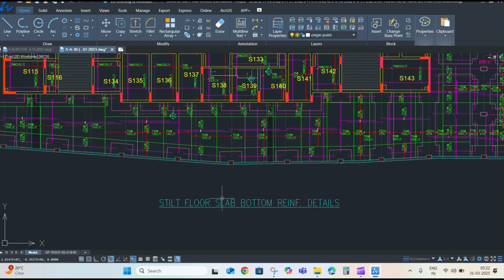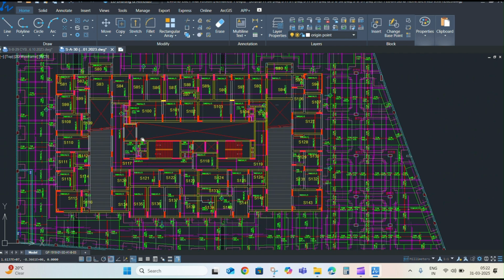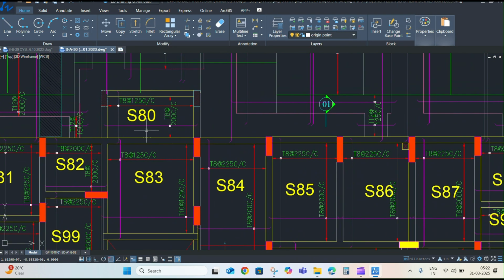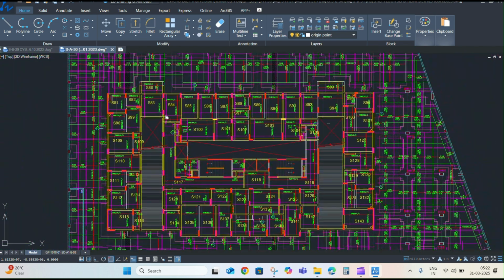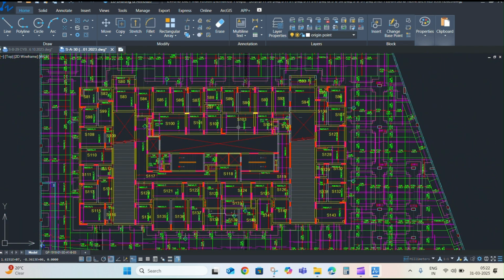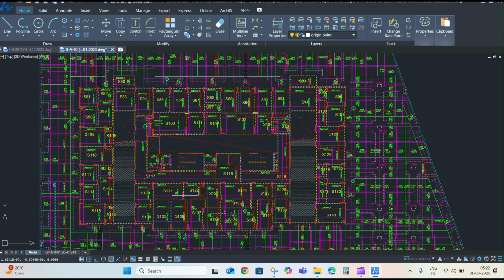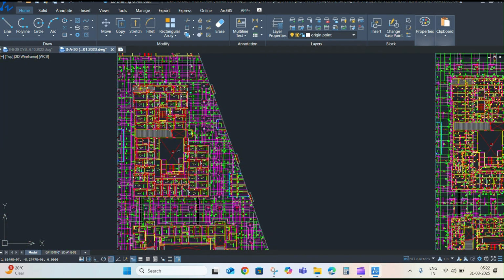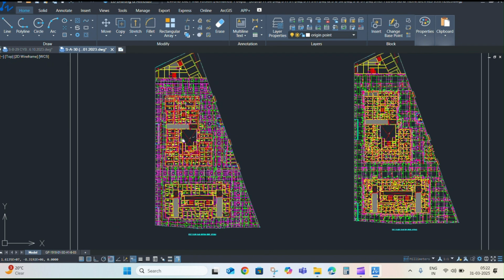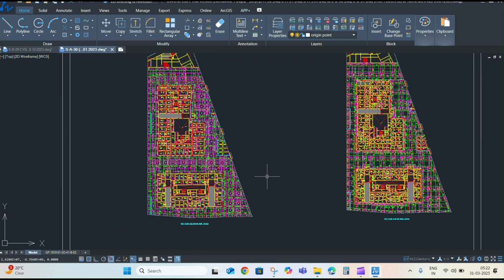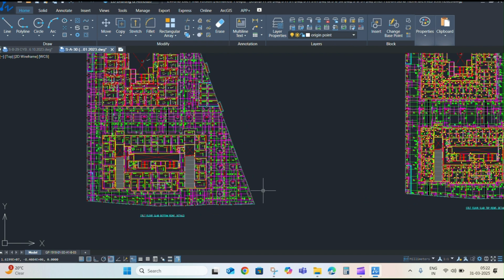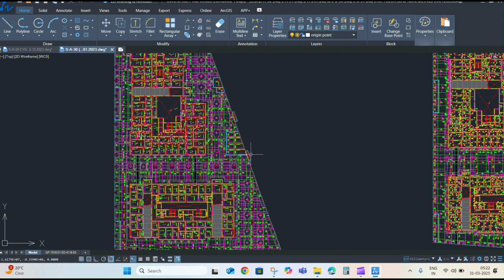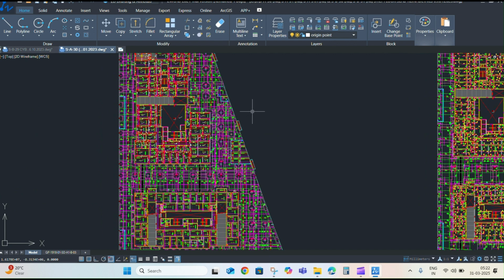size of elements correctly. Types of structural drawings. Foundation plans show the layout of footings, slabs, and the foundation system. Framing plans indicate the placement of beams, columns, and floor systems. Detailed drawings: detailed sections showing how components come together, such as connections between beams and columns. Rebar detailing: specific drawings for reinforcing steel placement in concrete elements.